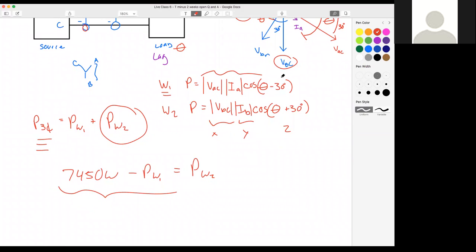Jonathan said, if they equal or don't equal, does that tell you power factor? Jonathan, are you talking about the individual powers? Yep, PW1 versus PW2. It does. There's a table. I don't have it in front of me right now, but I'm not sure if they'll always equal. Sometimes one might be 0, some's going to be positive, another one's going to be negative. Essentially, what that's telling you is your angle here, this theta.